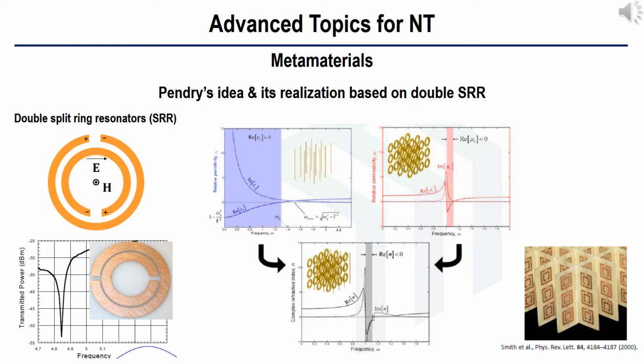One, optimizing geometry, has had limited success so far. Two, to incorporate gain can achieve zero loss over a broad frequency range, but it is difficult, complex, and expensive to realize in practice. Three, electromagnetically induced transparency, EIT, has very low loss, but does not maintain negativity in the real part of mu and epsilon. If realized, they are narrowband and involve using two different types of metals.